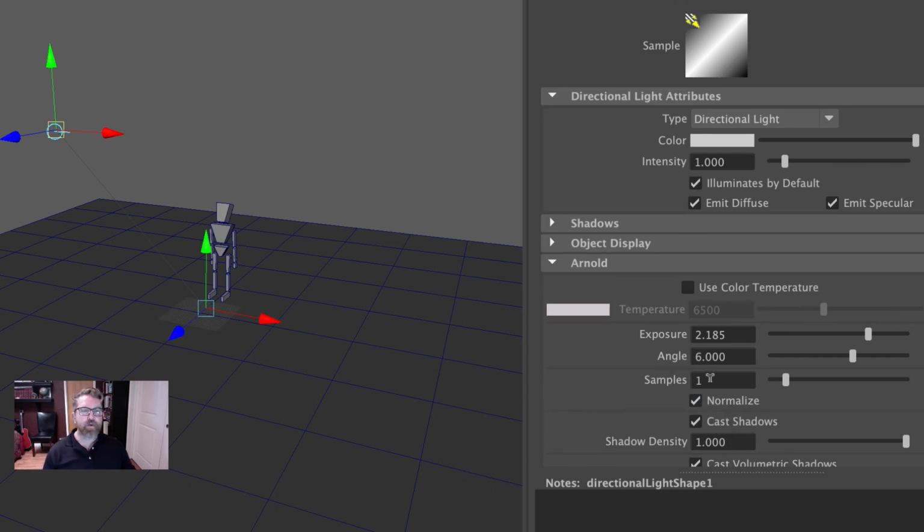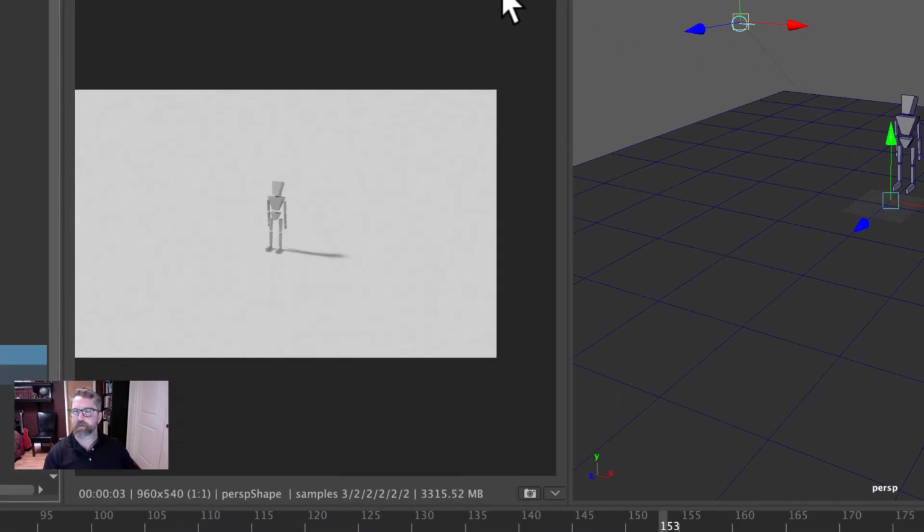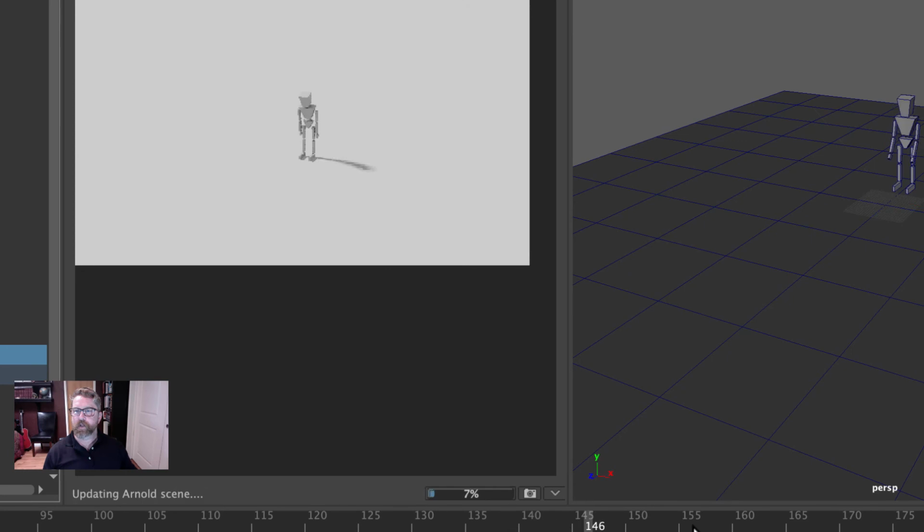And then it also warrants, the greater the angle, the greater the number of samples, which also increases your render time. So if your processor speed is slow, and of course this isn't a showcase project, you could just leave both of those at 0. But I'll go ahead and just put a 3 there. And we can see that that's what it looks like.